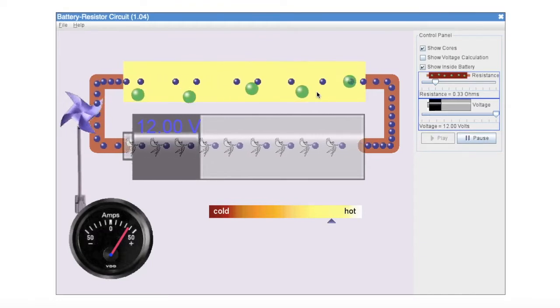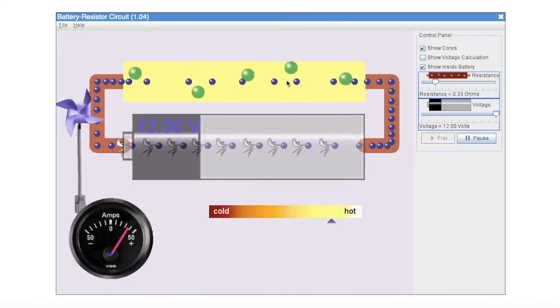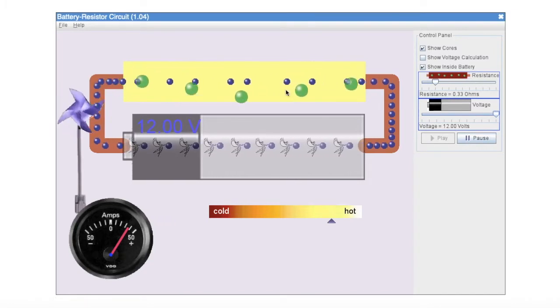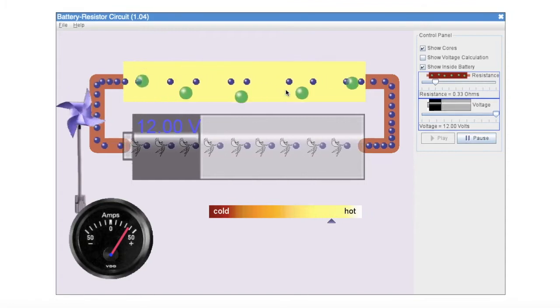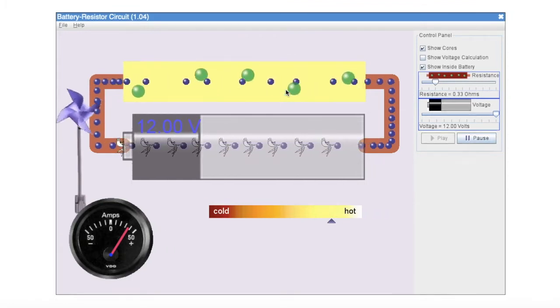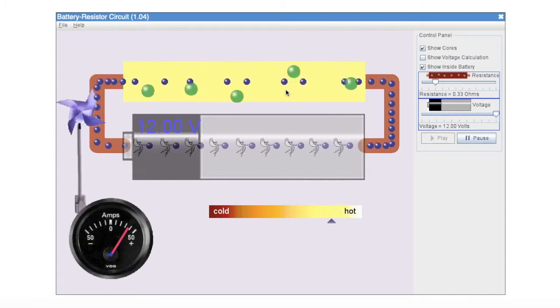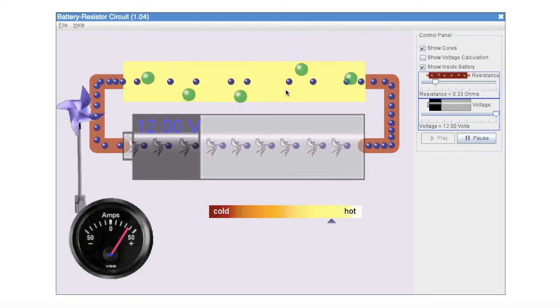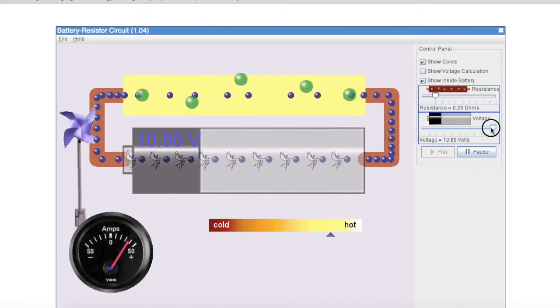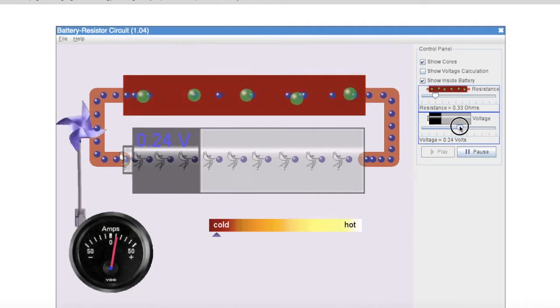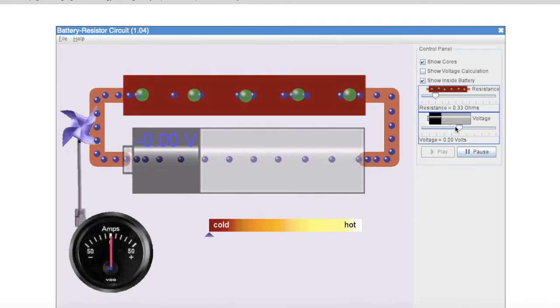That increment in resistance happened because the atoms of that conductor, since they have gained kinetic energy, were able to oscillate at a much higher amplitude and in a more frequent manner. Therefore, they were able to frequently intercept the passage of the electrons, which is none other than the passage of the electrical current, thereby incrementing the resistance of that conductor. To wrap it up, initially we started at 0 volts, where the atoms had their own natural vibrations, and the initial temperature of that conductor was at room temperature.